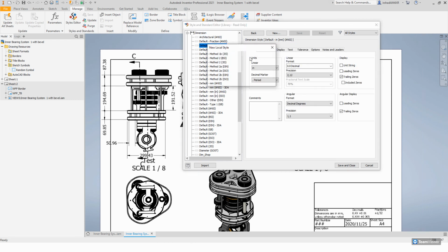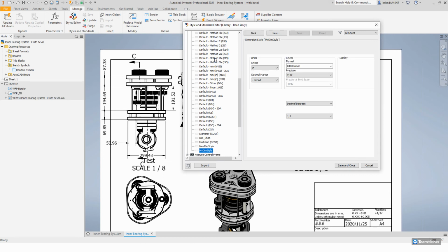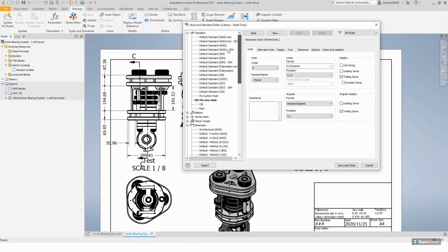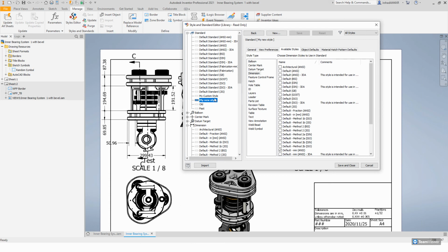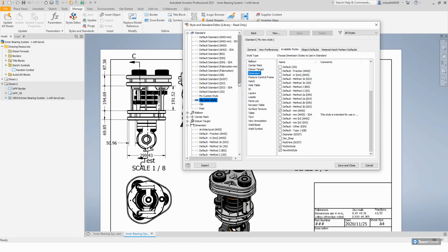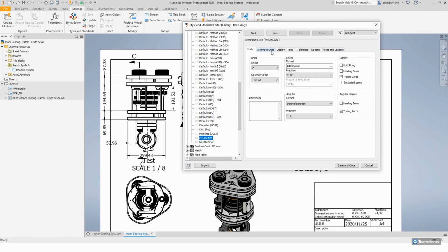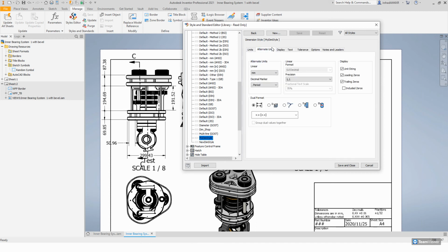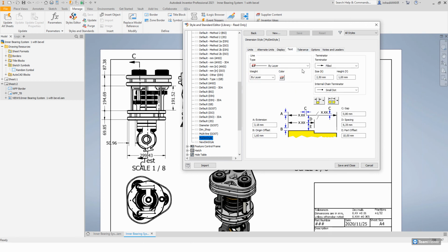And I'll just look at default new style. Okay. My dim style. You'll see the checkbox there was add to my new style, or add to current active style, meaning it adds it here so that I'm able to see it. My new dim style, there it is. Let's go back there. And you'll see that I'll be able to change exactly what I want to on my dimension.